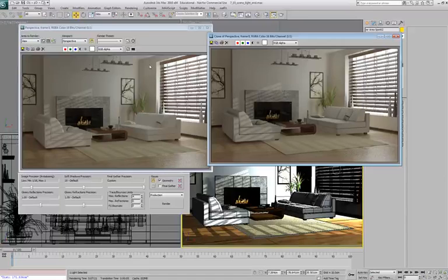What we want to do now, since we've got the global illumination, we've got the final gather turned on together, they look really well together. We want to go back in and we want to adjust the settings a little bit more so that we can get a higher precision out of them. So like with the image precision, let's go up to about a medium precision on here. On the default shadows, we could turn that one up. We'll take it up to a high quality 2x. With our refractions and reflections, the default 1 and 1 is going to be fine. And the other one that we want to look at